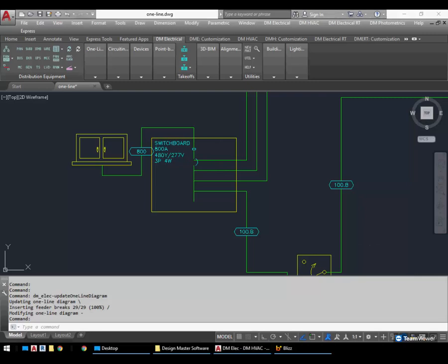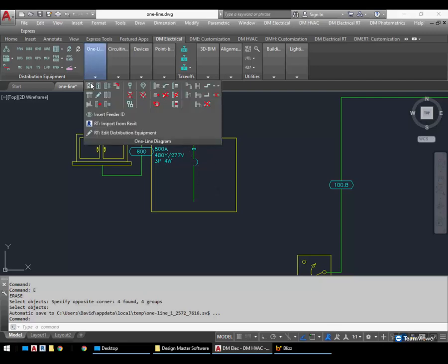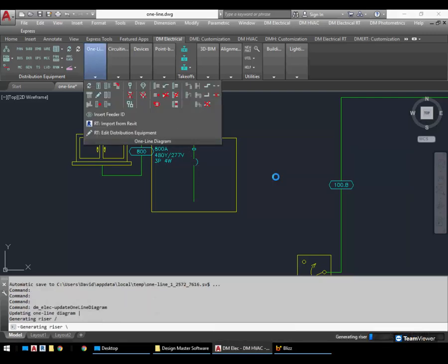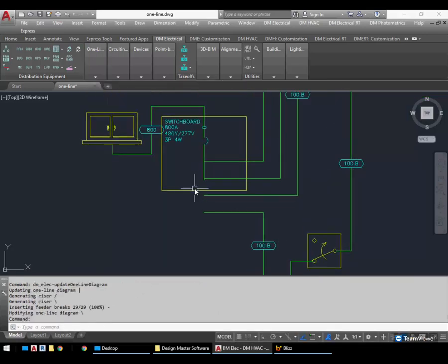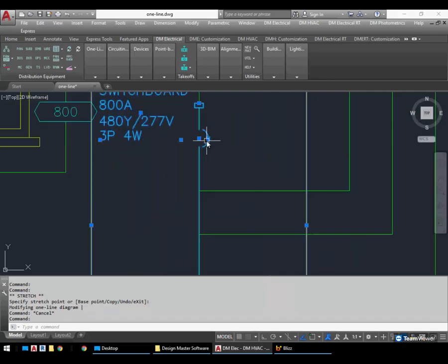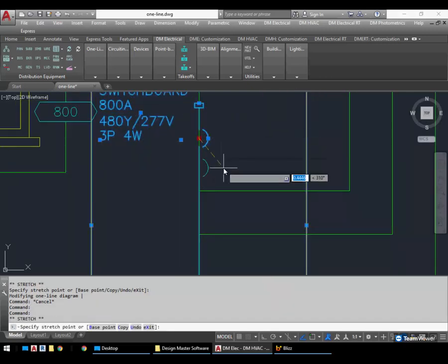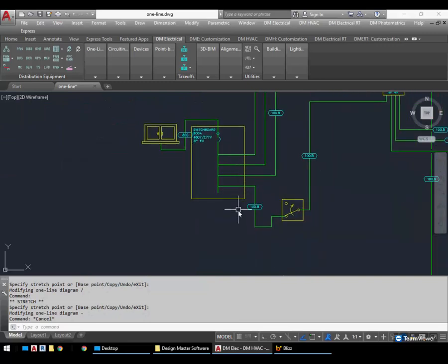So the circuit breaker ends up in one of two spots depending on how things are being generated. If you have a vertical panel like this, the circuit breaker just ends up in the bus bar. And then all of the circuits will end up below it, so we space them down nicely below it. And then we'll need to pull this whole thing down to get everything connecting. So that's where we put that. You can move this once it's in there if you don't like where we put it by default. But our best guess is a default spot, and then we put all the breakers below it.